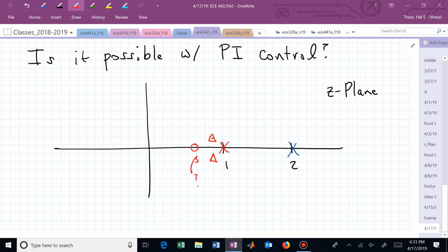If that triangle belongs to the root locus, what did we have relative to the root locus? We had 2 conditions, didn't we? We had a magnitude condition and a phase condition. Which one would tell us that that triangle is actually on the root locus? Or which one would we use to try to establish that? We want the phase to be at 180 degrees at that triangle,